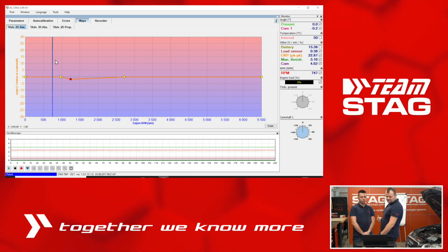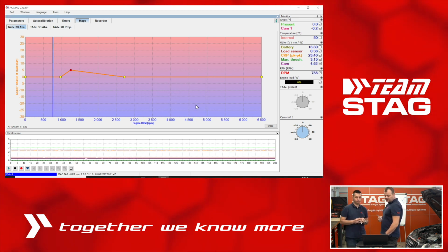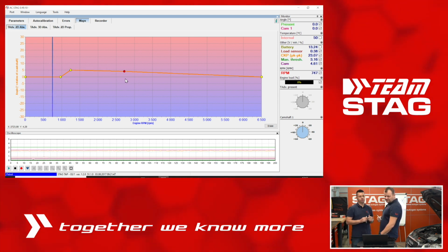And you can also retard ignition using TAP, for example if you are converting the engine from CNG to LPG, because the CNG default advanced ignition map will be just too high for working on LPG. That's why you can use TAP to retard the ignition. Normally, if we're going LPG, we should go, as the application shows us, maximum 5 degrees. This is a recommendation. In some engines you can go even 7 degrees, and it's still a good value to handle proper performance and efficiency.